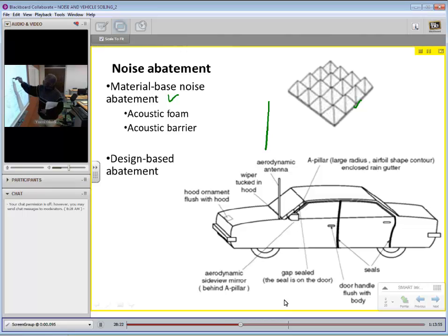Well, typical antenna design used to be just like that, and it goes to the vehicle, and the cross section would be something like that, of the antenna, just a little circle. Well, if there's going to be antenna in the vehicle, the designer might consider a cross section like that instead of that. Have a cross section like this, probably much more like this. But essentially having an airfoil tendency, rather than just having a circular tendency.